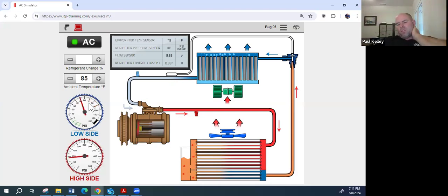That doesn't happen if there's no moisture in the system. The problem is there's moisture in the air we pump in the tire, because the compressor is pulling from the atmosphere and its humidity. If you did it with nitrogen, you wouldn't have that big of a temperature swing, but it's a major temperature swing when it gets hot, right? So if it was just the hot side spiking way up, I might consider going with air.